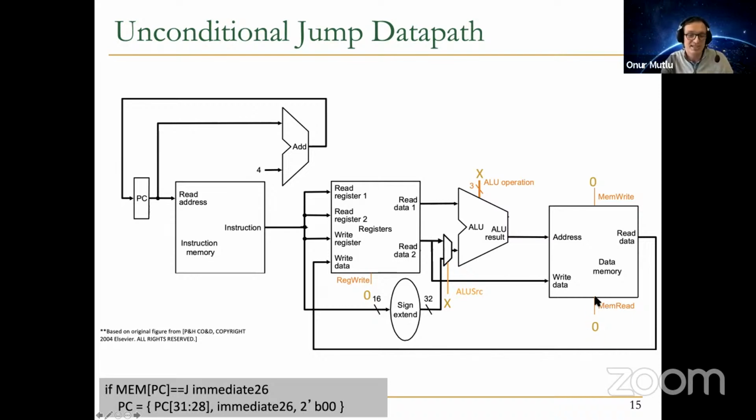So if you have a mem read signal that's set to 0, you can save energy. But you will see that in one of the other microarchitectures that we will examine quickly. In the book that you're reading, the Harris and Harris book, you don't have a mem read signal, and that's fine, because reading from memory doesn't do harm, right? It just potentially consumes more power. You could argue that that's harm, but it doesn't architecturally do harm.